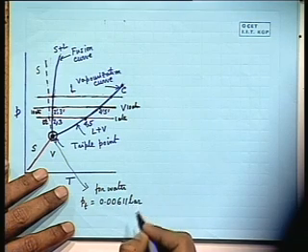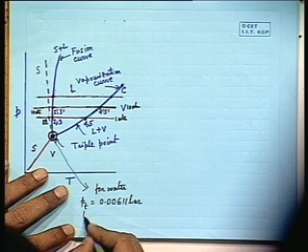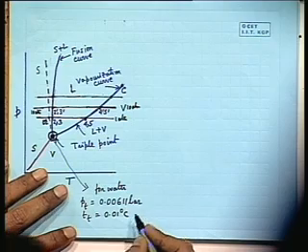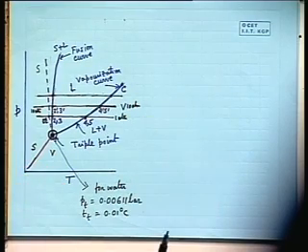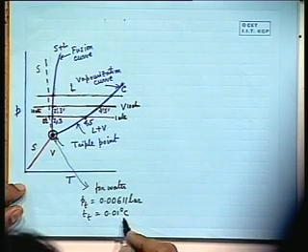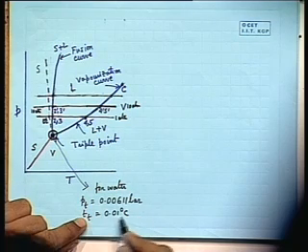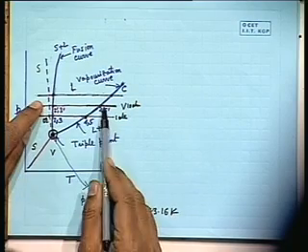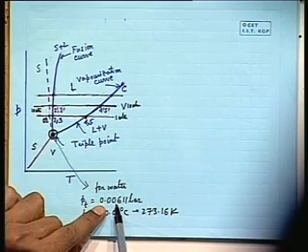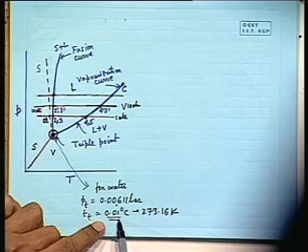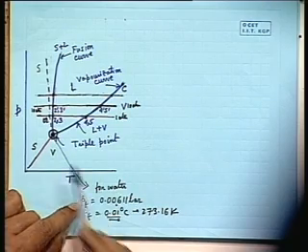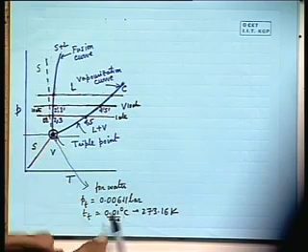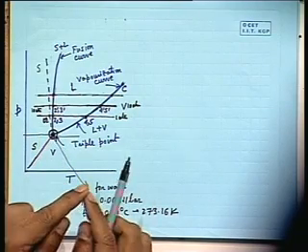For water, this PT is 0.00611 bar. You know bar, 10 to the power 5 pascals, and the corresponding temperature is 0.01 degrees Celsius, that is 273.16 K, since the conversion is plus 273.15. So you see, when you reduce the pressure from 1 atmosphere to this pressure, water boils at this temperature, and at the same time when you reduce the pressure from 1 atmosphere to this pressure, water also solidifies at this temperature. So this is the meeting point.